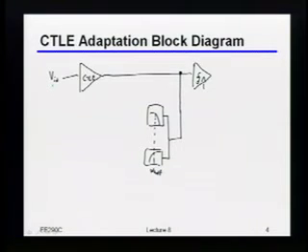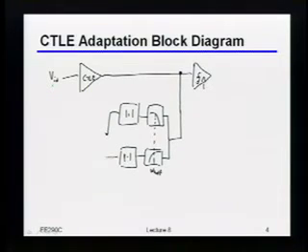Yeah, basically I just do a peak detection. So I do some sort of either squaring or rectification or whatever you want to call it. I'll just draw it as an absolute value here, although you should really think of that as being a rectifier or a peak detect. Then once I've got that, I know the energy in the lower band and the energy in the higher band. So now all I really have to do is compare them, so really just subtract them.